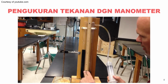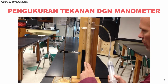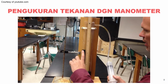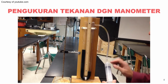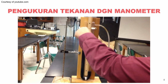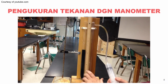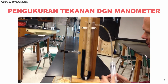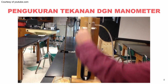So from this point here, I'm measuring 19 millimeters. Okay, now of course this I just measured 19 centimeters. So that's 190 millimeters of fluid I'm supporting upward. And I would say that the pressure in this area is higher than the atmospheric pressure pushing down. Right? Manometers use a differential of pressure to measure. So right now, the pressure in this syringe, which is connected, is 190 millimeters of mercury higher than atmospheric pressure.